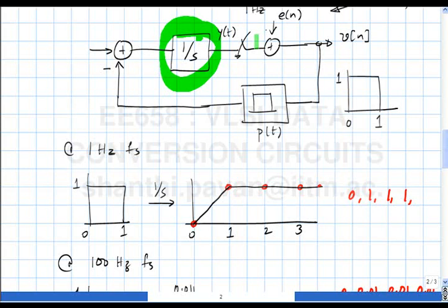So this now can be applied blindly to any modulator without even going and calculating the noise transfer function. Which is why I have said I will assume a 1 Hertz sampling rate throughout, because I can now not carry fs and 2 pi fs and all this other stuff, which will surely land me in some numerical mistakes.